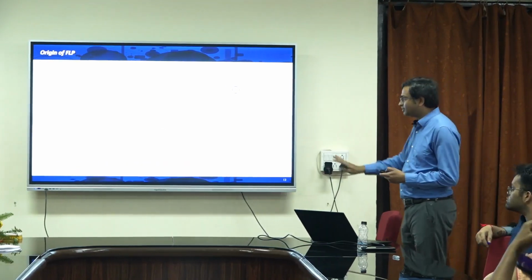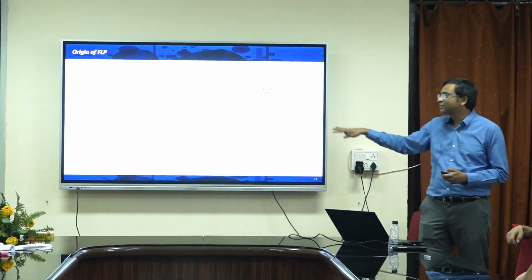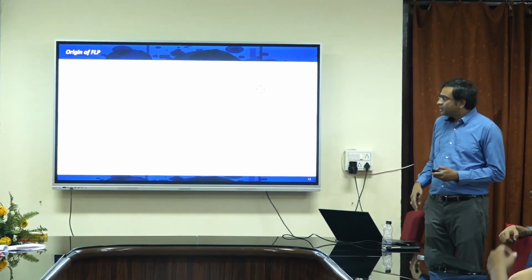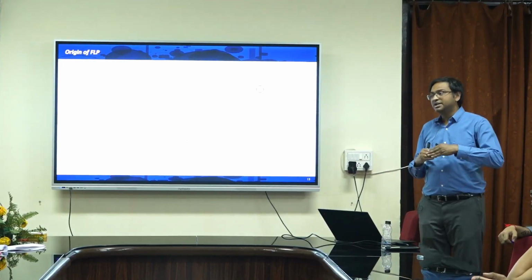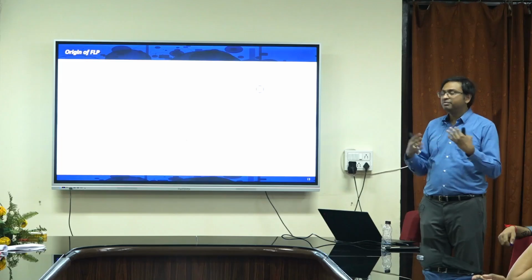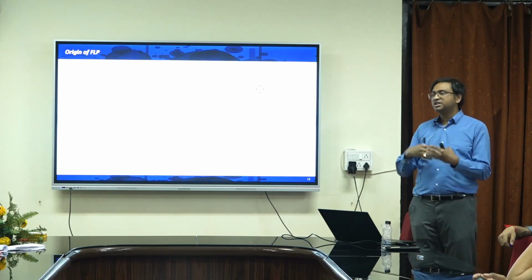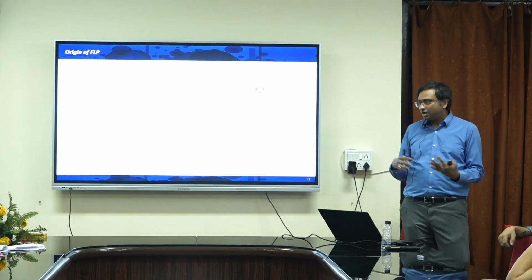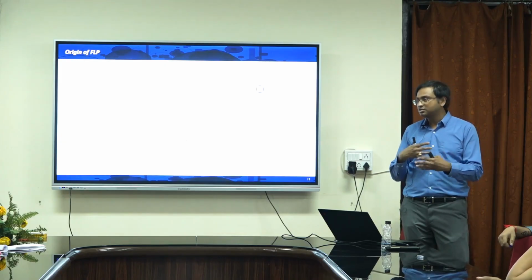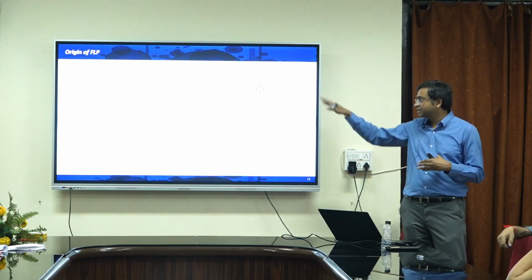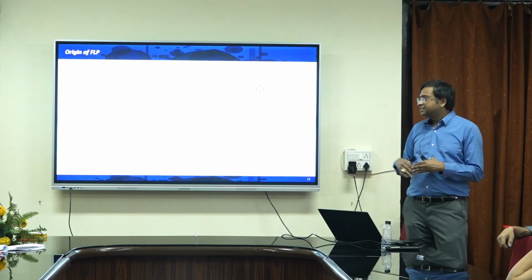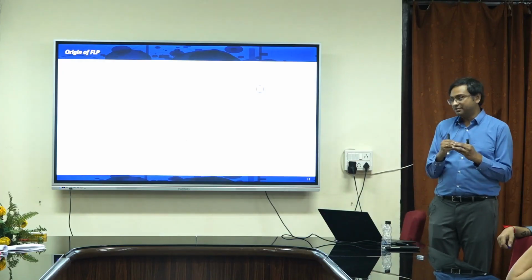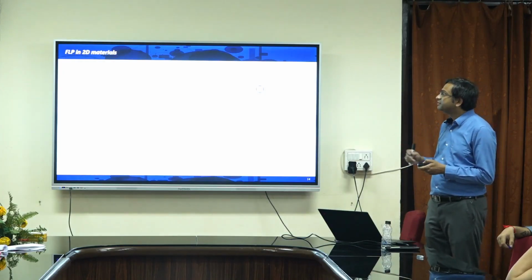We are not going to go into that, it is digging much deeper, let us not go there. But whenever you put metal on top of a 2D material, because of many reasons, could be the damage due to the evaporation, or exchange of electrons or holes between the metal and the semiconductor, there are some gap states, okay, and this gap state pins the Fermi level. This is called the Fermi level pinning, okay.